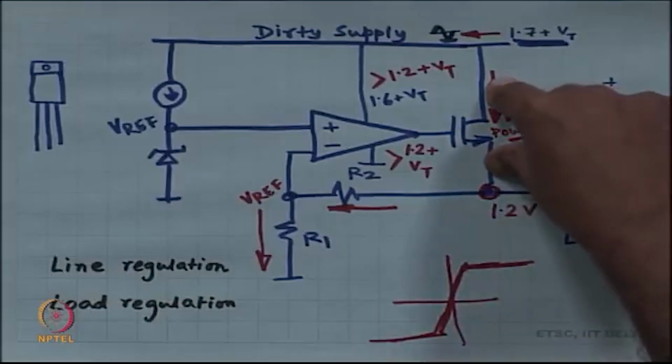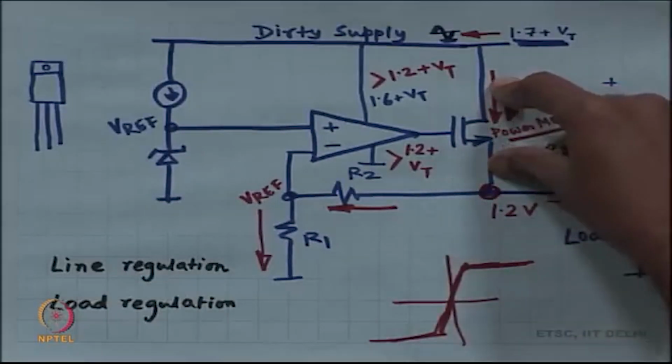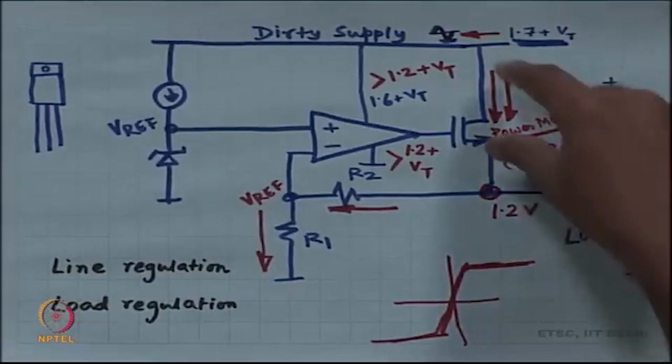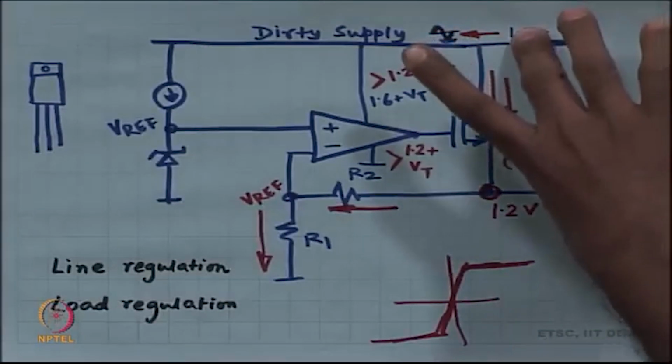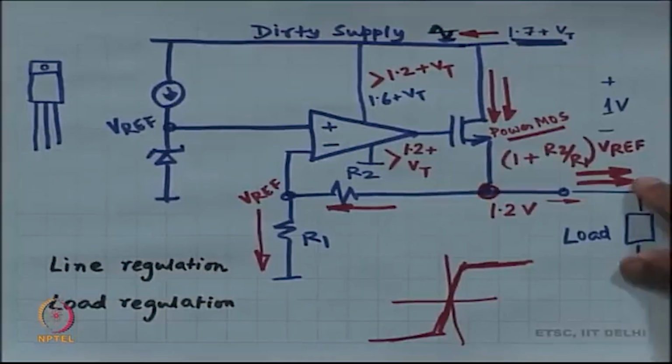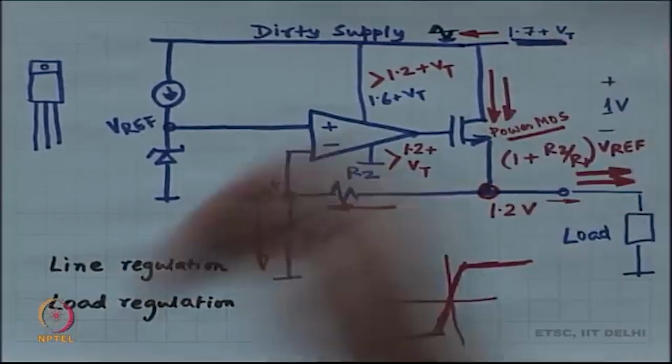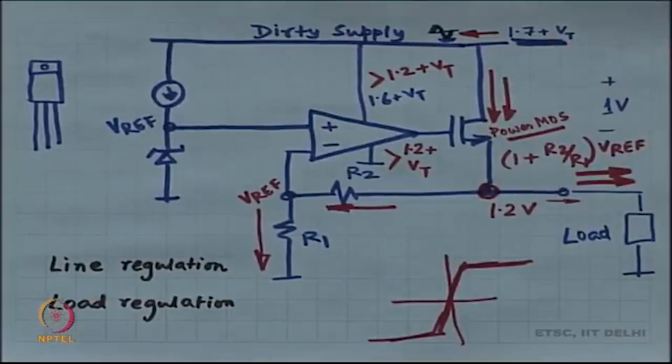What is the power used up over here? 50 milliwatts. 60 delivered, 50 used, net is 110. Okay. What is the efficiency? Efficiency is power delivered to the load divided by actual power drawn from the supply. So, that is 60 divided by 110, it is less than 60%, right, and this is happening in the power supply. Okay, this is a disaster,